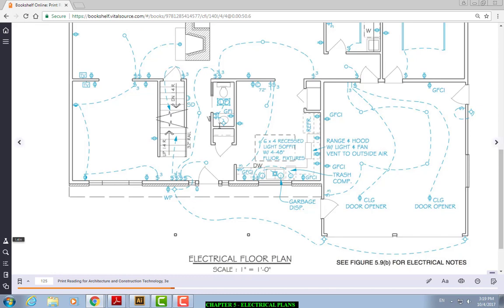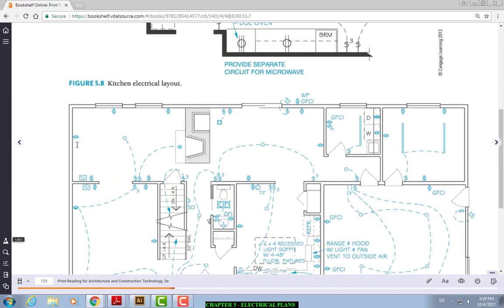So for example, you're doing a room, you have to think, am I giving enough outlets to provide the homeowner, or if it's you, to be able to shift stuff around? Because if you only put one outlet, then that means if you're going to have a TV in your house, it has to be on that wall. That's it. Because you only have it here, unless you want to have a cord going all the way to another side. So you have to think of those things. Where can I leave power for things that they might need?